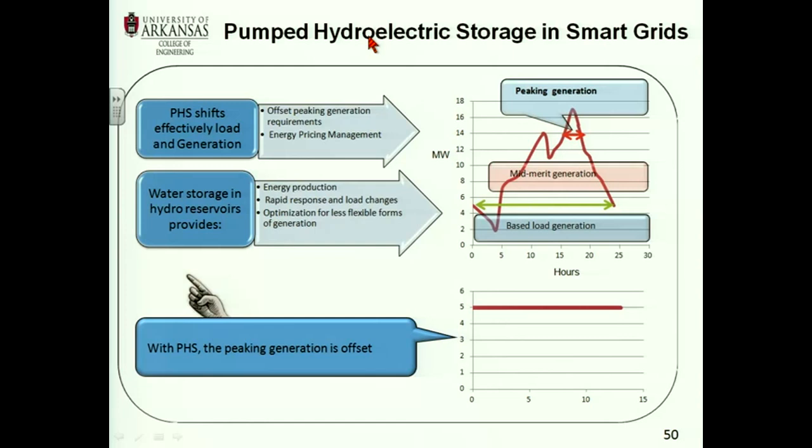Now the problem, if you are talking about 10 kilowatts, it's okay. The batteries are not big. But if you are talking about 100 megawatts, like in the case of a wind farm, now you need a lot of batteries. So pump storage is a better alternative. The problem, you need some reservoir, right? And here is where basically